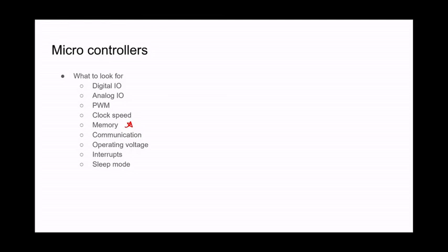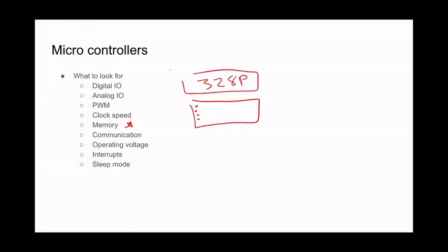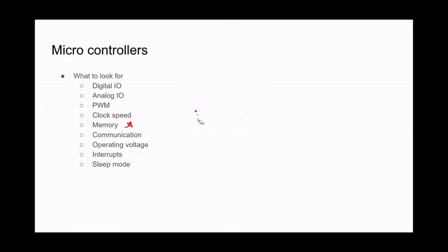For instance, we sell these little OLED screens. They're great. They're nice little compact things that have 4 pins. It's I2C communication. However, the default library to use these is large enough that you need the 328P processor, the Arduino package, for instance, the ATmega 328P. If you don't have that big processor, if you're using the 168, it's not going to fit. It just can't support the entire library that you need to use that OLED screen.